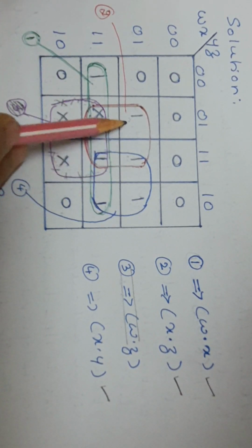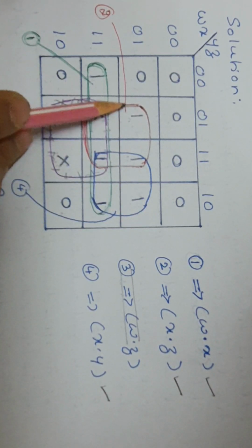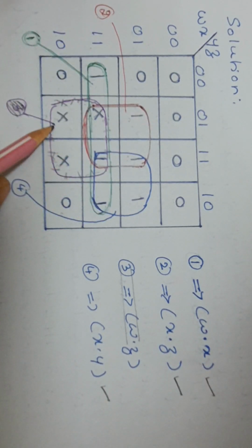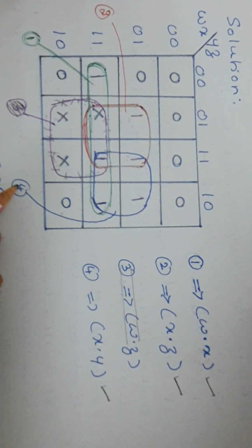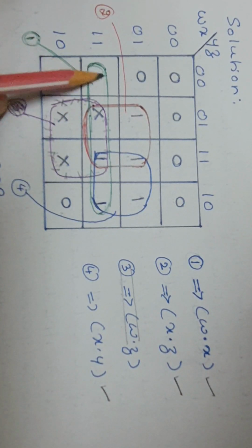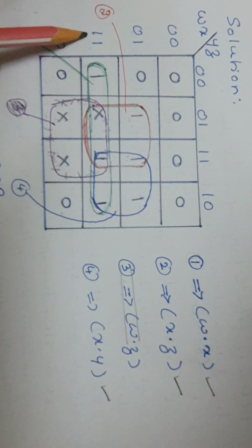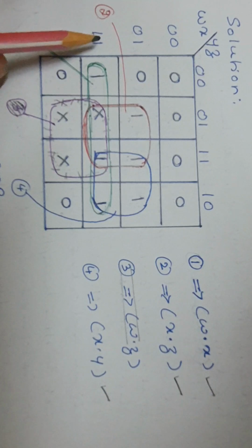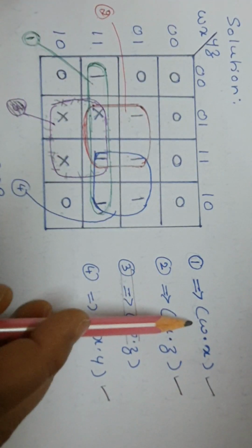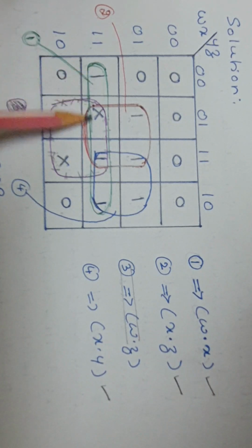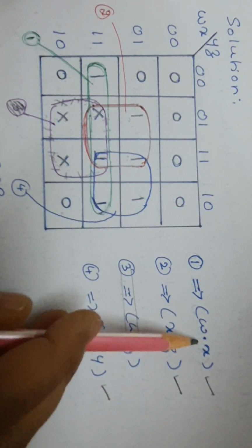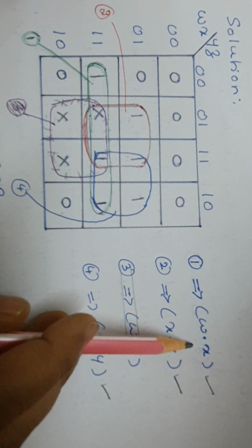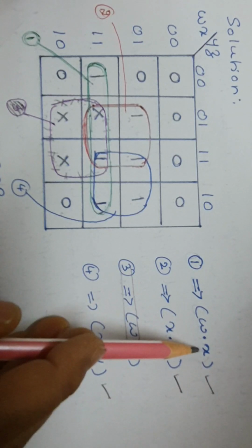Okay. Then this is one group, this is second group. So this is the first group I have marked, this is the second group I have marked. This everybody might take, that is third. This I have taken as the fourth one. So with respect to the first group, all these 4 ones are covered in this row 1 and 1. So that is Wx we write, with respect to the first group. All these ones cover 4 columns. In these columns nothing is common, that is why only what is common row wise we have written for the first group, that is Wx.